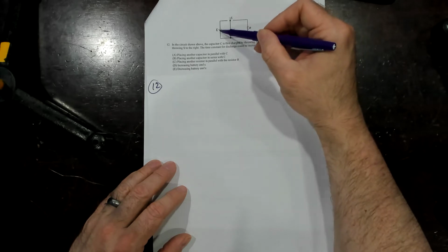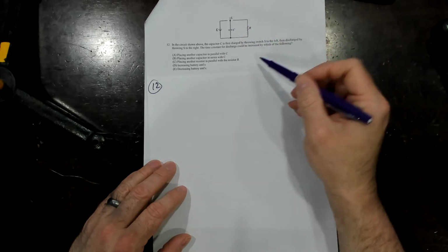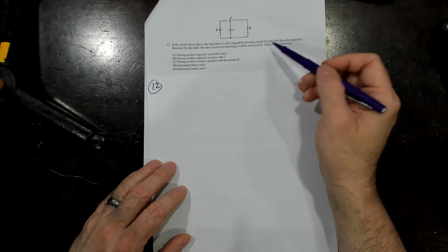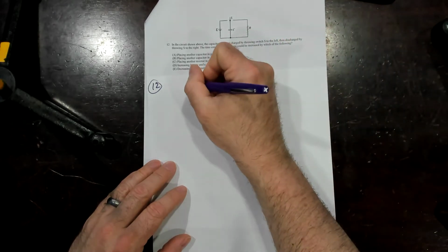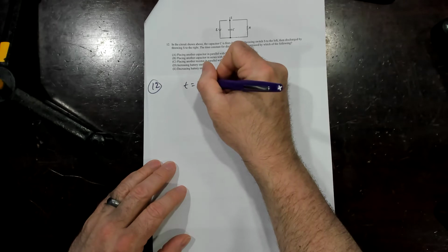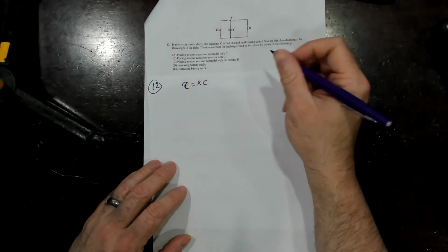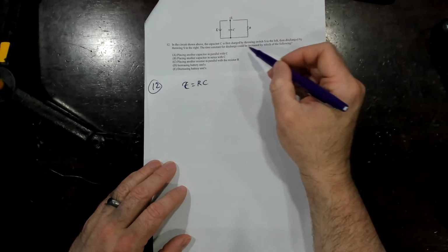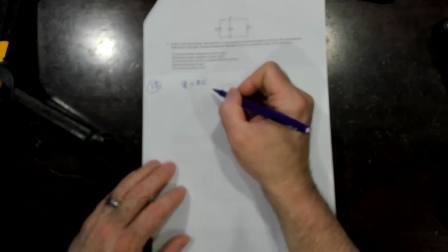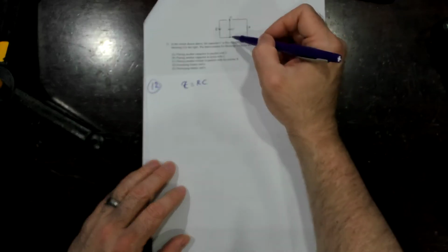Okay, so current will start to flow this way onto the plates, and then when I close the switch here, it'll discharge around that way. What they want to know is what's the time constant for discharge. You say, well, you should just know that in an RC circuit, again, I know I'm using the same thing twice on this test, sorry, that the time constant, tau, is R times C. And so if I want to increase the time constant, then I need to increase the resistance or increase the capacitance. We'll put another capacitor in parallel with C.